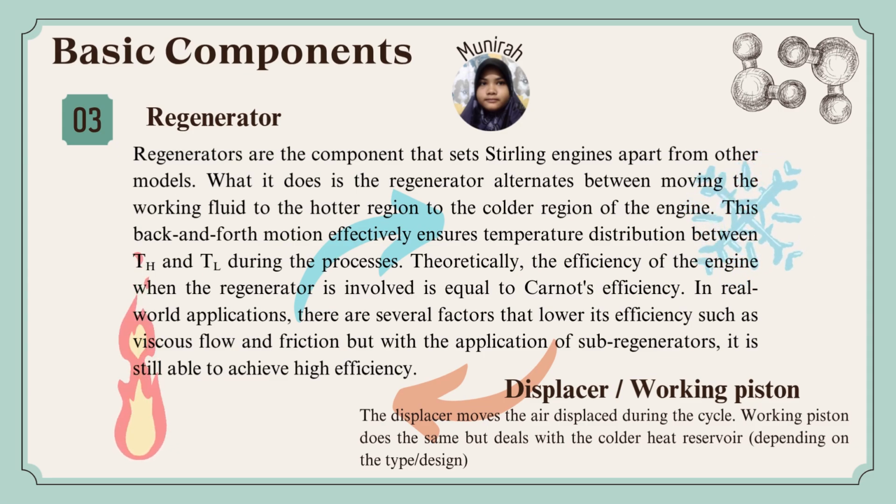As the plunger displaces air, it exchanges heat. The plunger was the name for the displacer and regenerator. But the alpha type engine differentiates between a displacer that displaces the air, a working piston that regulates the pressure, and regenerators that are made up of fine wire mesh that absorbs and releases thermal energy.